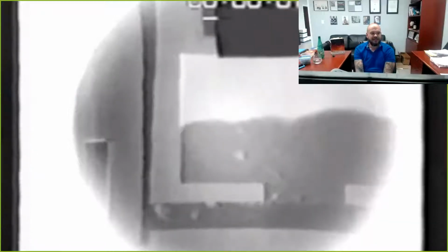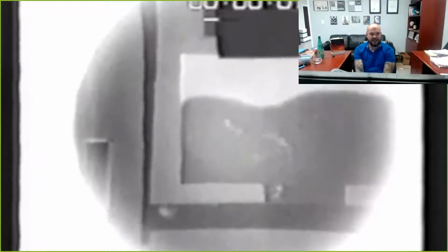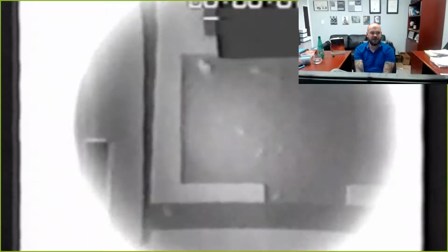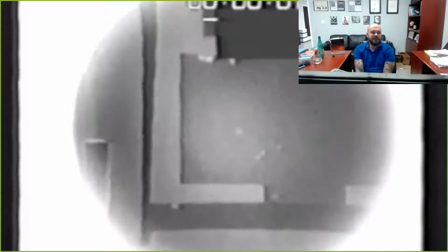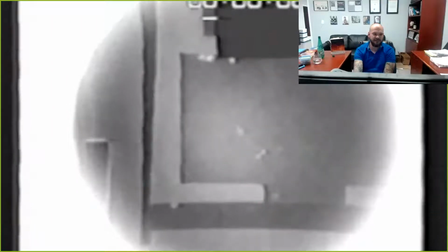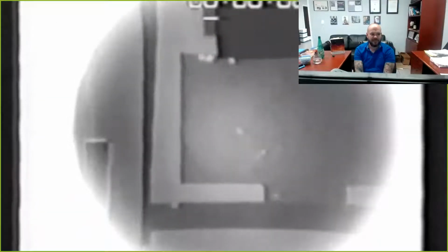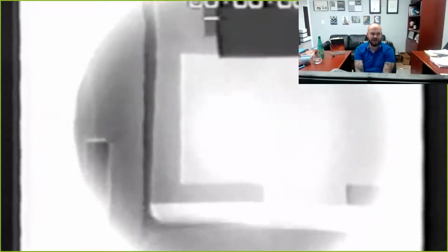Perfect. All right. This video is from the University of Birmingham in 1993. And this is live video X-ray work that was set up by John Campbell. And the purpose of this was, let's figure out what the hell's going on when we're pouring a casting. And you can see when we're watching this video, the vast amount of air, I'm going to play it again, that is aspirated during the pour. And all those air bubbles that you see rising up through that melt are leaving an oxide film trail in the wake and resulting in a perfect pre-existing crack through the metal.